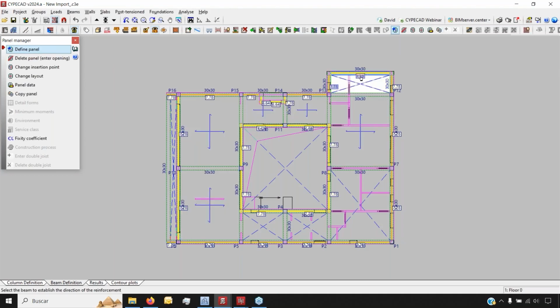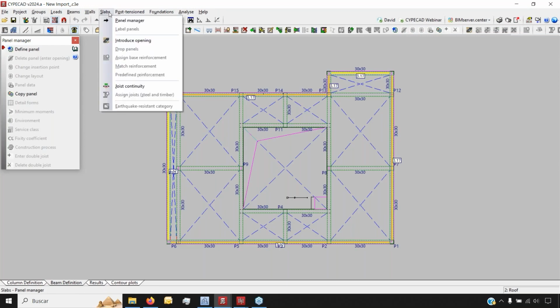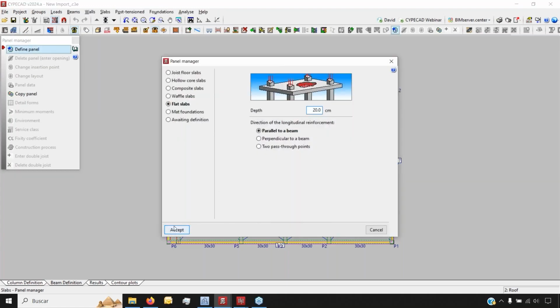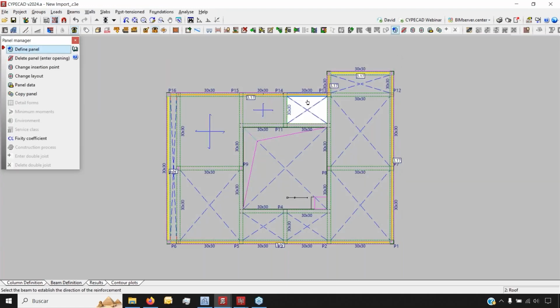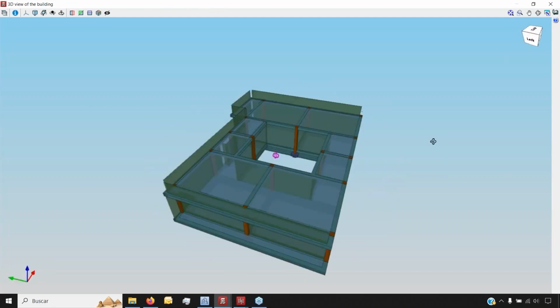And you can see that in a very short span, in less than an hour, we've been able to design a whole structure from scratch, either based on a 2D drawing or on an architectural model like this one. And we've been able to perform automatically the analysis for all the elements so that CYPECAD can design the rebar for us, check it against the building code, and generate all the reports and drawings that we mentioned before.